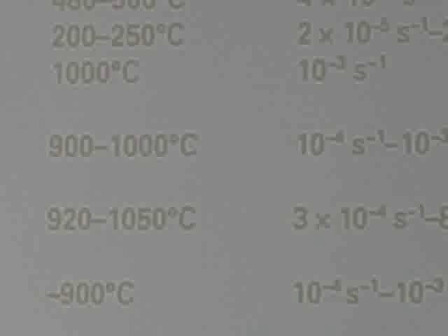Now, there are lots of different alloys that behave superplastically, not just titanium. Aluminum copper alloys, notice 33% copper. I mean, it actually is the copper intermetallics, but nonetheless, if you started looking at the phases, zinc aluminum, here's the zinc aluminum, zinc 22 aluminum. So this alloy is 70% zinc and about a third aluminum. 22 by weight, but by volume percent, aluminum is lighter than zinc. And that's superplastic at 200 to 250. It's one of the reasons Backofen did it. He liked to use low temperature systems, it's easier. That occurs over about 2 orders of magnitude in strain rates.